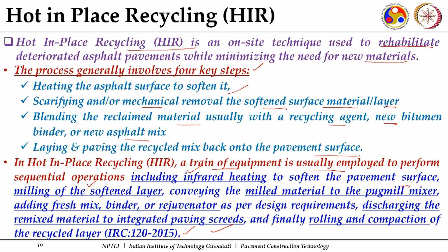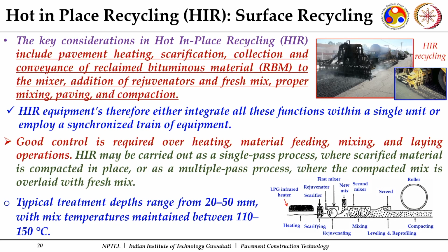So these are the key features of hot in place recycling, which we can also call in situ recycling. This is a big train, a set of equipment in line. So we will look at the key considerations in hot in place recycling: at what temperatures the pavement needs to be heated, up to what depth it needs to be scarified, collection and conveyance of reclaimed bituminous material, RBM, addition of regenerators, fresh mix, fresh binder, fresh aggregates, and thereafter paving and compaction.